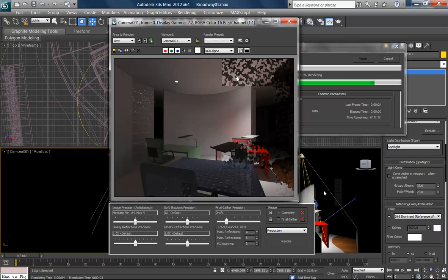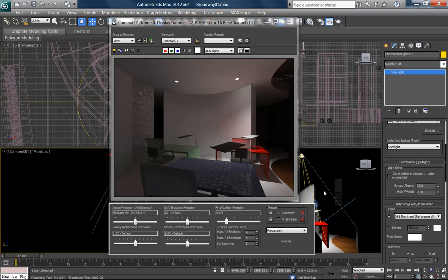So that's really clear. So you've got those hard-edged shadows, and that's because we've just got the one light source, and it's coming from a point of light in a cone shape, and using these things called ray trace shadows, which basically project very accurate rays. That can be a good thing, but it's also pretty unrealistic.